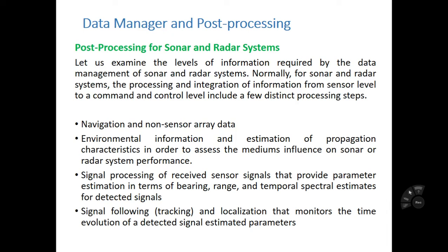And then the signal processing that provides parameter estimation in terms of bearing, range, and temporal spectral estimates. Finally, the signal tracking and localization that monitors the time evolution of the detected signal's estimated parameters.